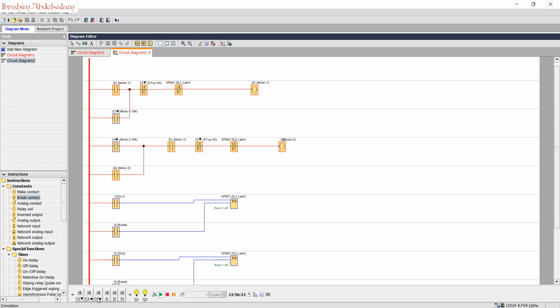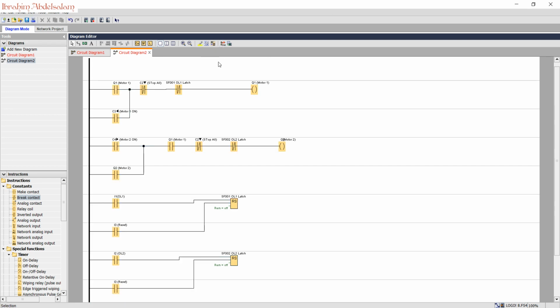Start motor 1, start motor 2. We have an overload signal in motor 1. Oops, the two motors immediately stop. So we have this wrong scenario. We expect only motor 1 to turn off. So let's see what's wrong in our ladder diagram.